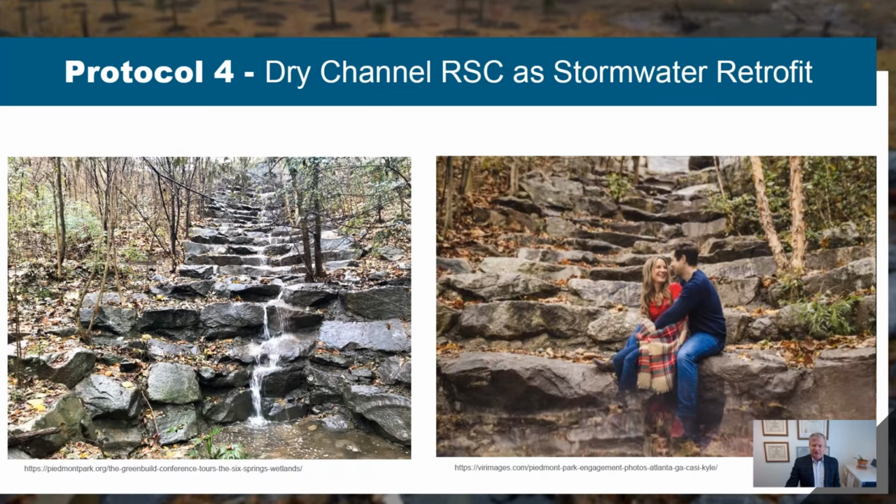During high flow, it acts like any other boulder step pool, but it gets rid of all that grout and other things that could actually add pollution into our streams through algae, pollution through temperature, and creates a BMP, which is more like a sand filter or bioretention basin. These are meant to be no maintenance, or at a minimum, very low maintenance outfalls.